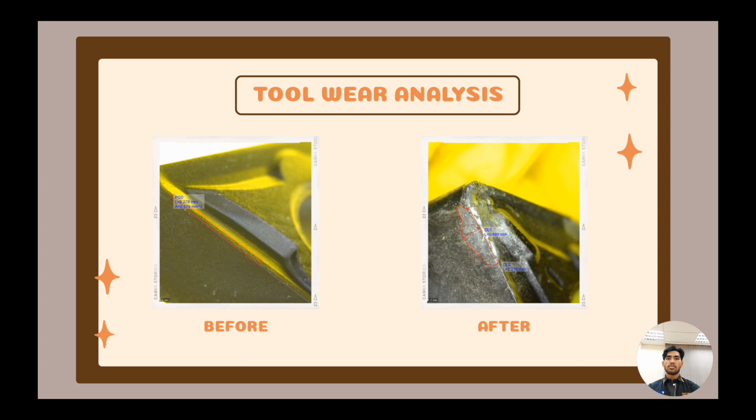The lead tool we use for this project is a tungsten carbide which has 3 corners and edges. The point of this lead has its own chip breakers which help to remove chips more easily and well. The first picture, before, is the unused point tool or new lead cutting tool. If you look closely using a Dino-Lite microscope, it has no wear and has a good profile.